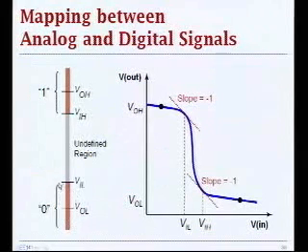So what the noise margin tells you is basically how much you can deviate from this nominal value and still be able to interpret your output signal as either logic 0 or logic 1. For that purpose, we will also define these VIL and VIH signals.